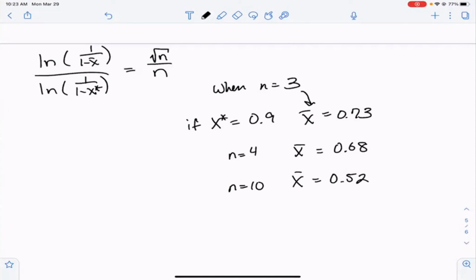Well, some of it is, we know that we have to increase the velocity. Now, there's 2 sides to that, because you also decrease the residence time when you do that. So mostly what you would have to do here is to design your system with the ability to tune the velocity, and also perhaps even to make the reactor length a little bit longer than you would from a design perspective. And this helps to build redundancy into the process.